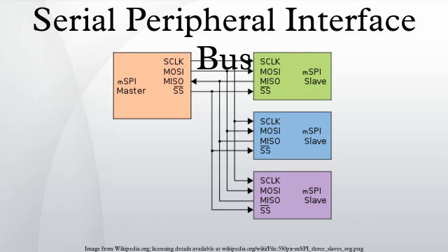Slaves do not need a unique address. Unlike I2C or GPIB or SCSI, transceivers are not needed. Uses only 4 pins on IC packages, and wires in board layouts or connectors, much fewer than parallel interfaces, at most one unique bus signal per device. All others are shared. Signals are unidirectional, allowing for easy galvanic isolation, not limited to any maximum clock speed, enabling potentially high throughput. Disadvantages: requires more pins on IC packages than I2C, even in the 3-wire variant, no in-band addressing.